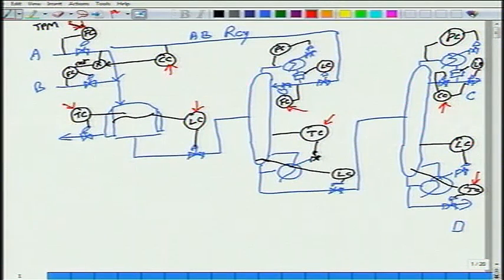Conventionally, we are used to looking at a control system that is feed downstream. What we drew last time was we had the throughput manipulator either at the product stream here or here. And when we had it here, the level control was in the reverse direction of flow.